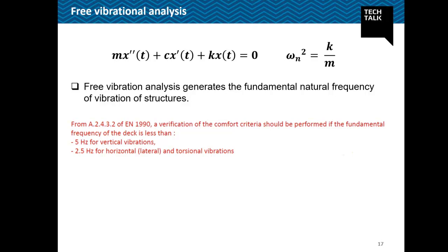As per Eurocode, we need to check the comfort criteria if the fundamental frequency of the deck is less than 5 Hz in the vertical direction, and if the frequency is less than 2.5 Hz in the horizontal or torsional vibration. Once we perform the free vibration analysis, we'll find out the fundamental natural frequencies in Z and Y direction.